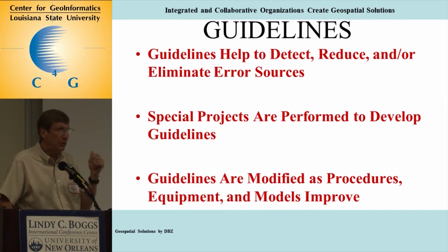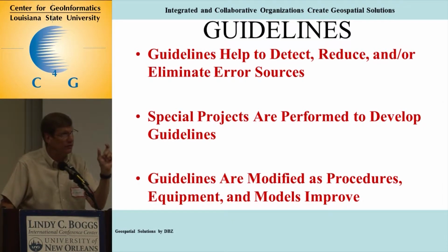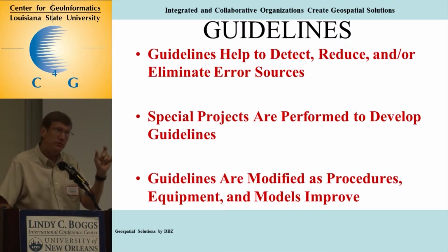In the guidelines, you're required to occupy the baseline twice. And there's a reason for that. Just like in leveling, a forward and backward run, it takes and helps to reduce the mean value that you're going to end up with. So when you do your adjustment, you have additional data observations. So you're going to get a better value because you repeated it.